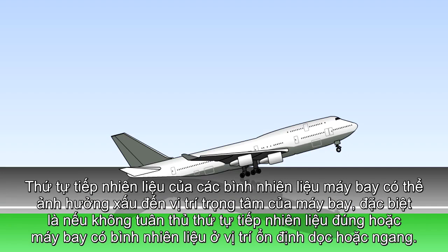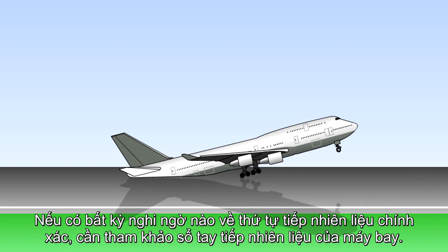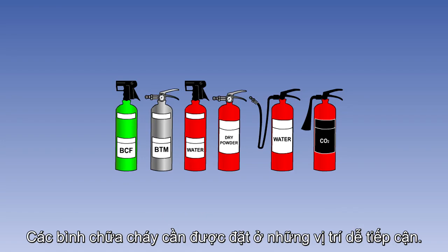The sequence of refueling the aircraft tanks can adversely affect the aircraft's center of gravity position, particularly if the correct filling sequence is not followed and/or the aircraft has a vertical or horizontal stabilizer tank. If any doubt exists about the correct refueling sequence, the aircraft refueling manual must be consulted. Fire extinguishers should be located so as to be readily available.